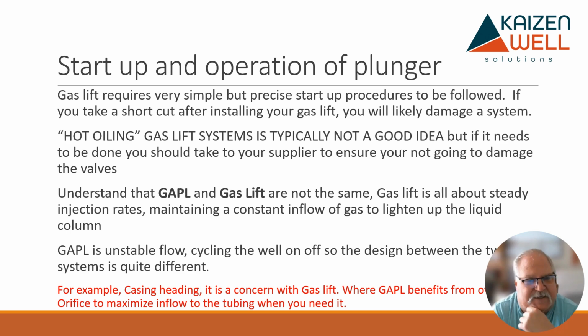So it's something that you need to work on. It's better to deal with it with chemical and things like plungers or Gapple than a bunch of hot oil if you can. Understand that Gapple and gas lift are not the same. Gas lift is all about steady injection rates, maintaining constant flow of gas to lighten up the liquid fluid. Gapple is really in the unstable flow. You're cycling the well on and off, so the design between the two systems is quite different.